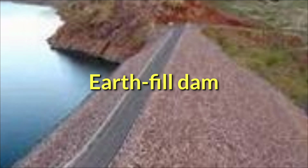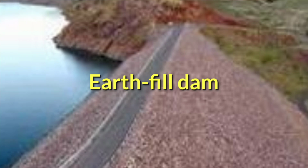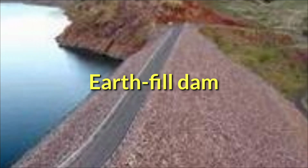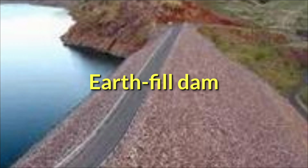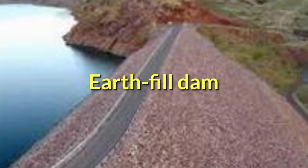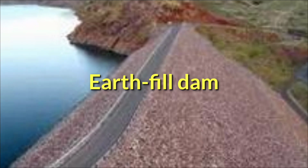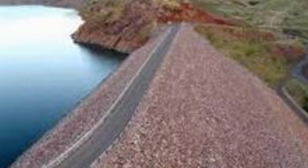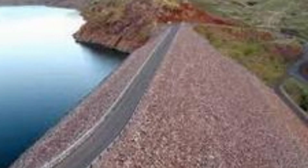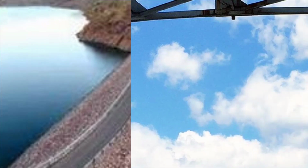Earth fill dams, also called earthen dams, rolled dams, rolled earth dams or simply earth dams, are constructed as simple embankments of well compacted earth. A homogeneous rolled earth dam is entirely constructed of one type of material but may contain a drain layer to collect the seep water. They can be effective in the regions where the cost of producing or bringing concrete is prohibitive.